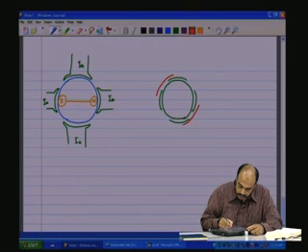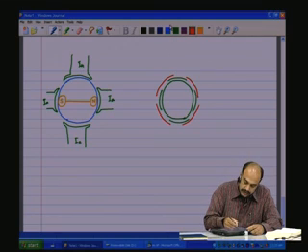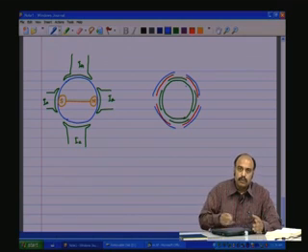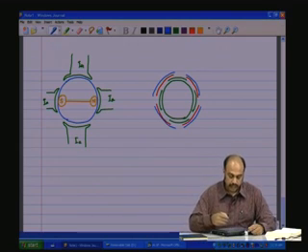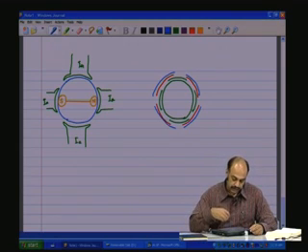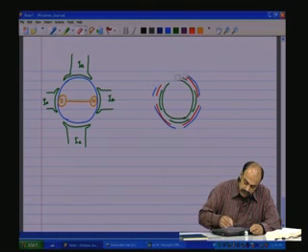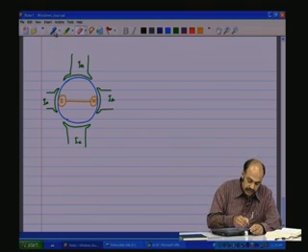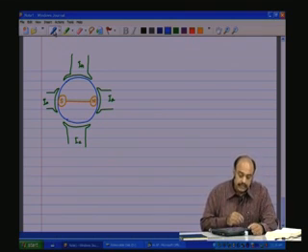You have one here, like that, and like that, and the C pole set is again shifted 120 degrees, will be in this manner. Only it is minus 120 degrees. The winding sense is changed from clockwise to anti-clockwise to obtain the 3 phases. So anyway, let me explain it with respect to only one phase to give you the idea of how the synchronous frequency changes with the number of poles.